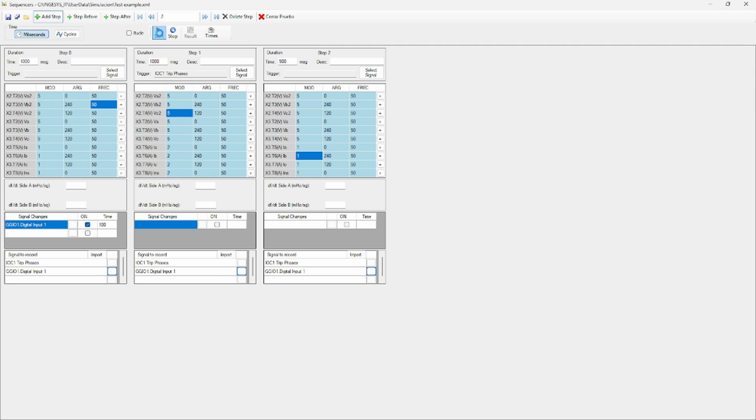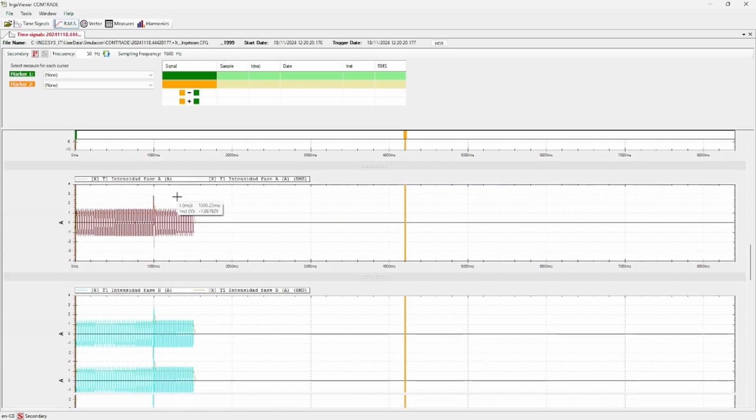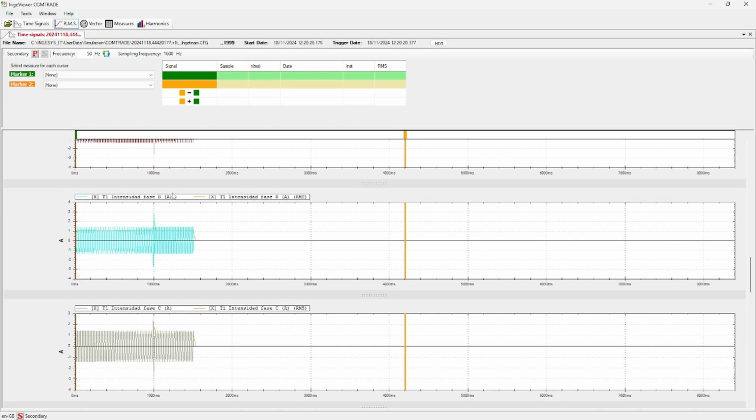During the simulation, some of the buttons in the window will be disabled. After the simulation, these buttons and tags will be enabled, and the results of the simulation will be available in the Result button with an oscillography icon. This button will lead us to the oscillography viewer, the ComTrade viewer window, where the simulated sequence and the fault caused by it shall be carefully analyzed.